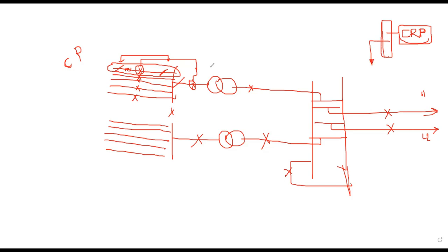Before going into this, I need to talk about a concept: centralized and decentralized architecture. See, I am having a panel here, and again a panel here. So every breaker unit has a panel. So 10, 11, 12, 13 panels are required on the 33 kV side, and 1, 2, 3, 4, 5 panels are required on my 220 kV side.